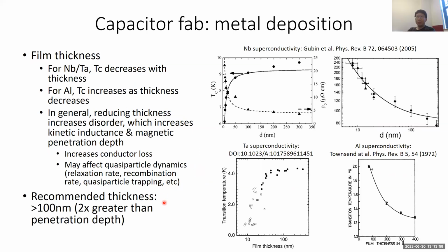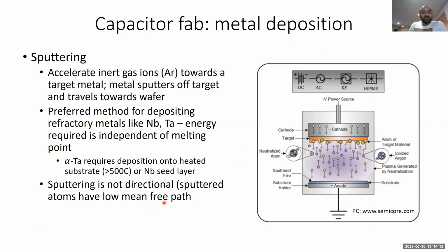Just to interrupt with one quick question. So is aluminum not preferred to be deposited by sputtering? I think you just commented on you cannot do sputtering for the junction. How about for the capacitor? Yes, you can sputter aluminum totally fine for the capacitor. Just making a junction using a sputtering process, at least in the more standard way, using double angle deposition, which I'm going to go into detail later on in the talk, is not really possible to do with sputtering, as far as I know.